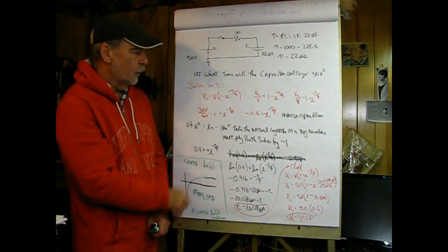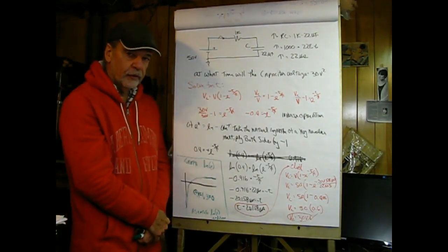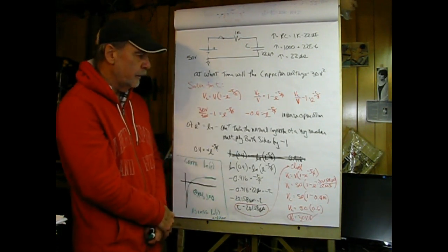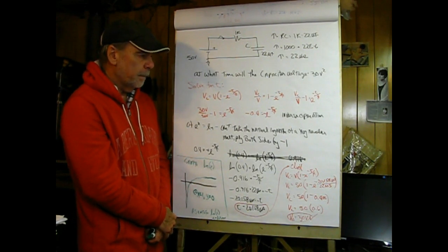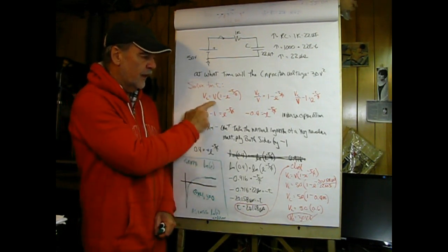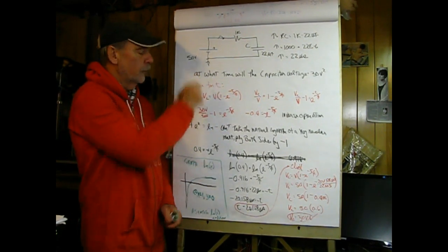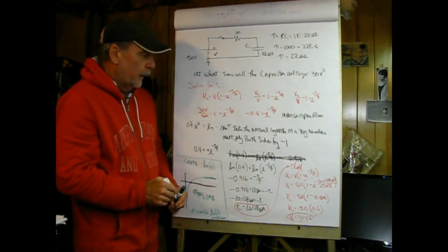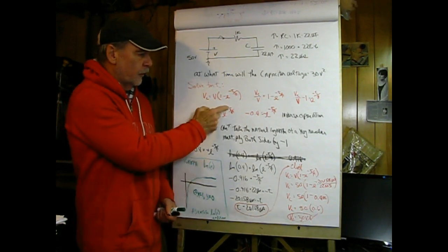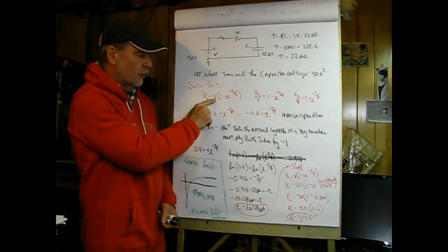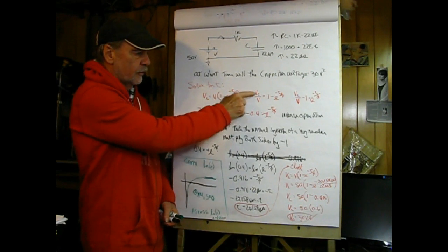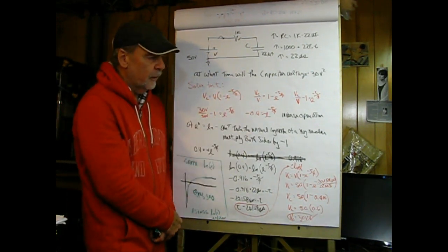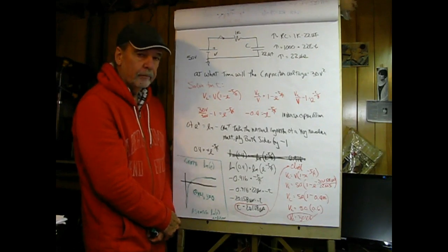Next, what we have to do is solve for t, which unfortunately is in the exponent of our natural number e. So we have to isolate that. And to do that we'll start by isolating the variable, dividing both sides by our V here, which gives us VC over V, and that's going to be equal to 1 minus e to the minus t over tau.